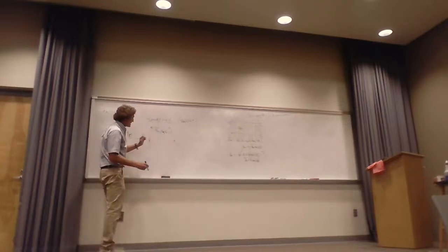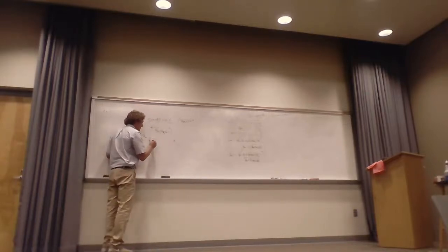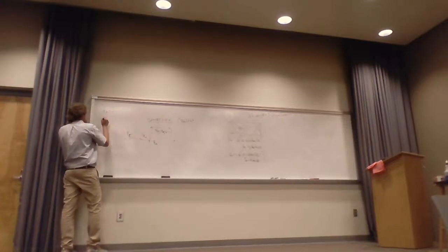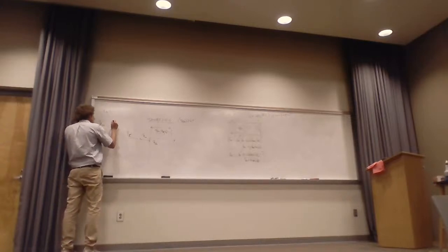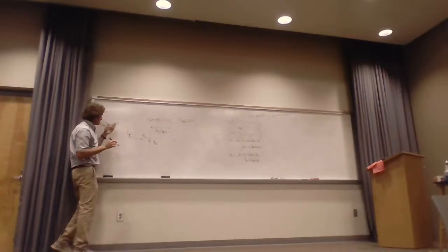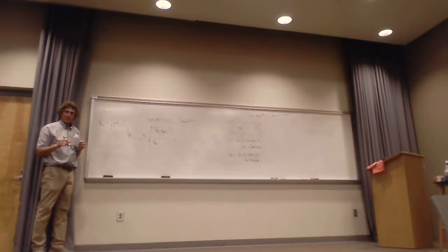Here, this is like Z naught, and that would be eta of the shield, right? By the way, I didn't put it down there, but eta of the shield would be equal to the square root of j omega mu over sigma. You can just say it's about that, and you can forget the j omega epsilon. With me, guys?